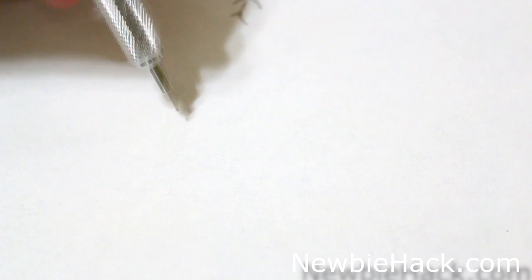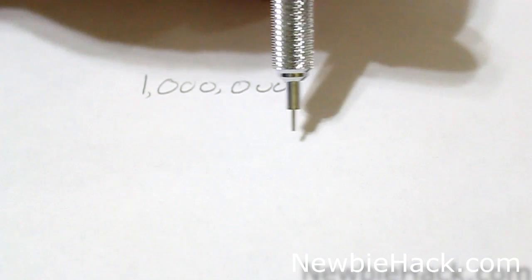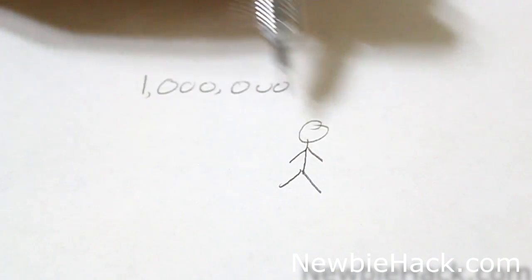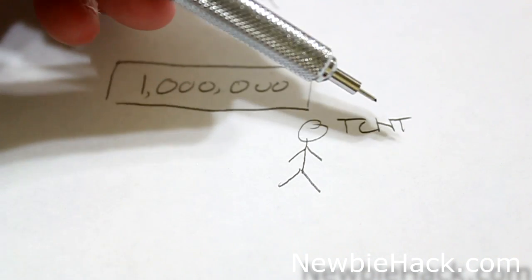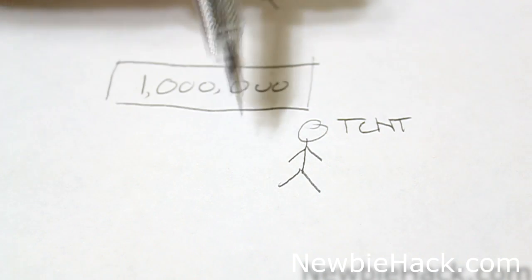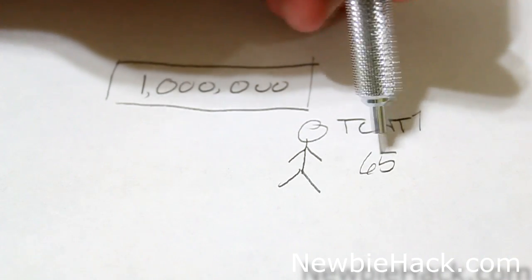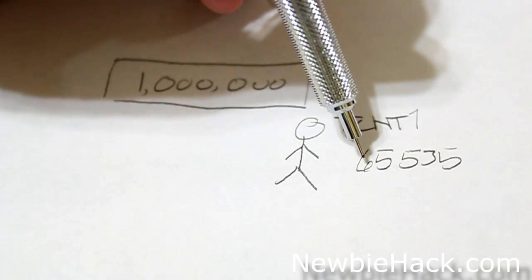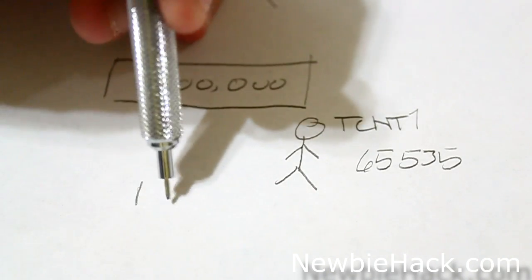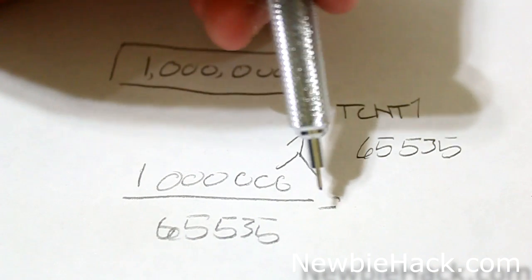Let's determine what prescale we need. We know that the AVR chip will count up to 1 million every second. So if we use a prescale that Mr. TCNT can count up to, that covers the entire quantity, then we'll be okay. Let's say we know that TCNT1 can only count up to 65,535. So if we see how many parts 65,535 go into 1 million, if we just divide that, 1 million divided by 65,535, we will know what prescale we generally need to be.